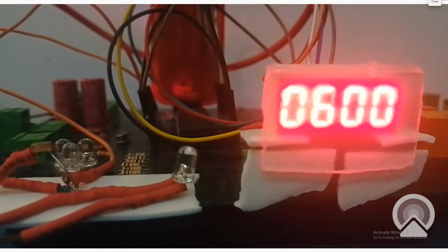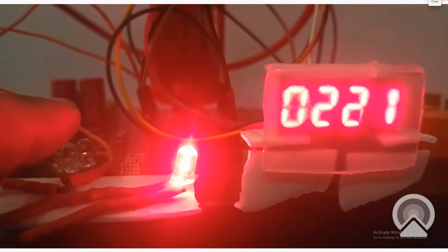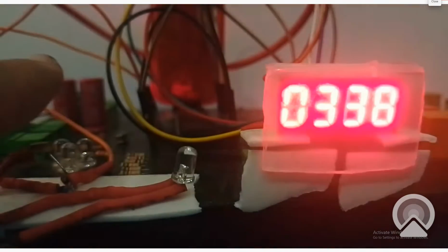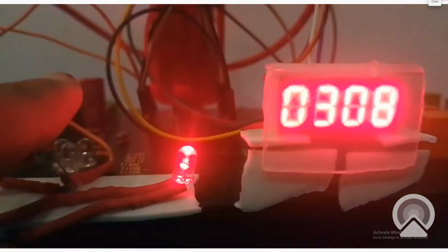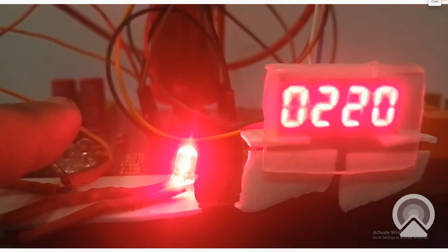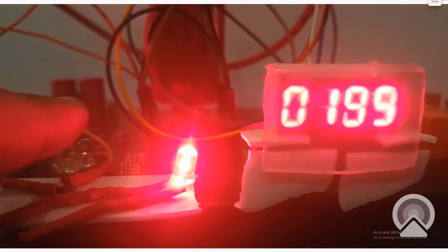So by default the value is 600. It means the light at this point in the room is the 600 value. So I had set the threshold to 300, so that whenever it goes darker than 300, the LED turns on. See, the LED turns on whenever the value falls below 300, and when it goes above 300, it turns off. At this point it's conflicting, above or below 300. So whenever the value goes below 300, the LED turns on, else it's off.